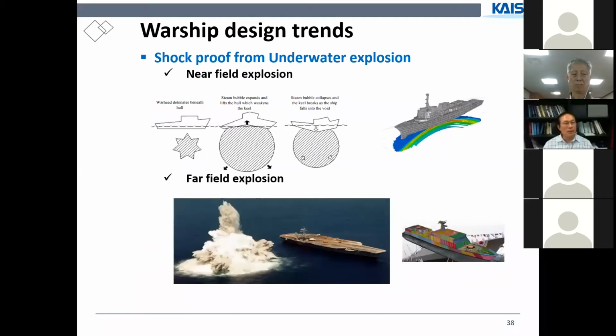And another thing is shock-proofing against underwater explosion. Underwater explosion has two categories: near-field explosion and far-field explosion. Near-field explosion: when the warhead detonates beneath our ship, first the bubble expands and lifts the hull upward.